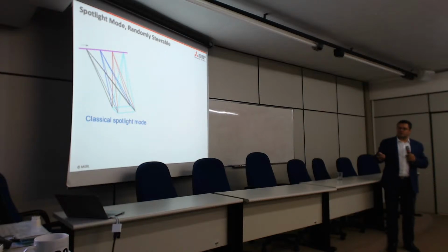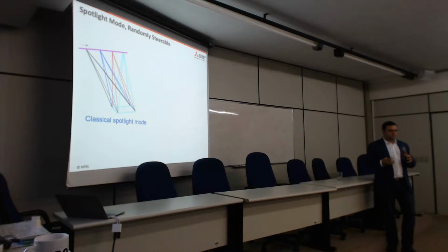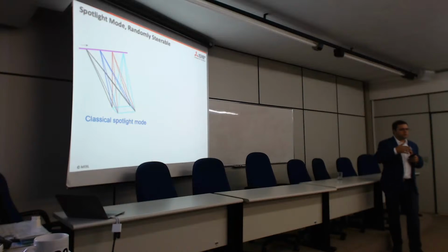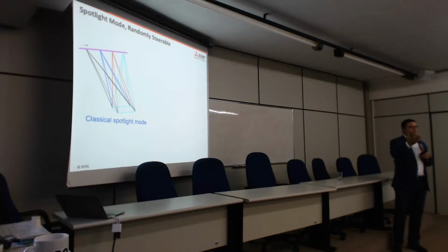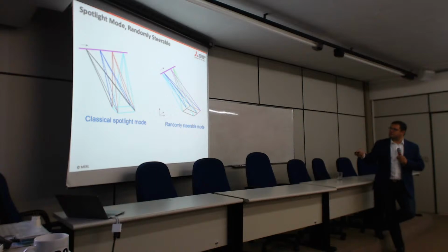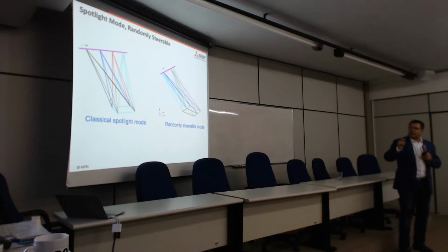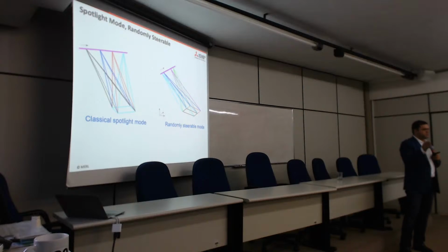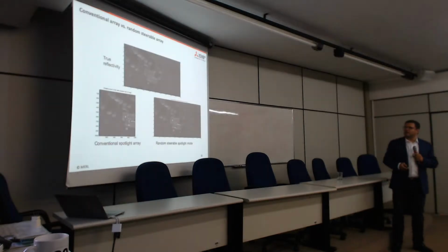We know that using ideas from compressed sensing and computational sensing, we can do undersampling. We can use fewer pulses, as long as we use some non-uniformity and some randomization, and then use computation to improve the reconstruction. So instead of always looking at one spot, every pulse will be randomly split between one spot or the other. So we will randomly look at 2 different spots and steer randomly. And this is what we get.